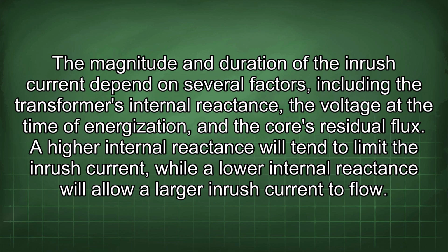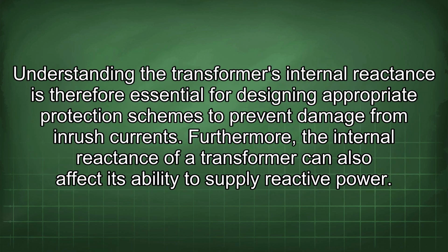A higher internal reactance will tend to limit the inrush current, while a lower internal reactance will allow a larger inrush current to flow. Understanding the transformer's internal reactance is therefore essential for designing appropriate protection schemes to prevent damage from inrush currents. Furthermore, the internal reactance of a transformer can also affect its ability to supply reactive power.